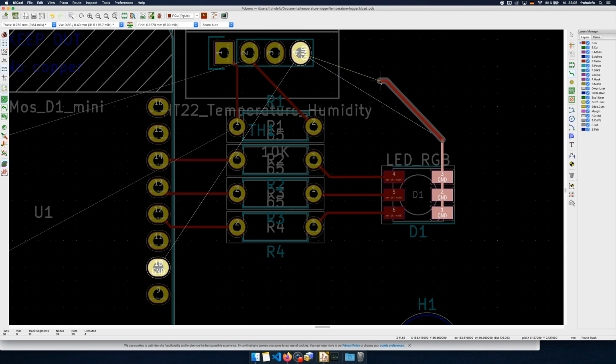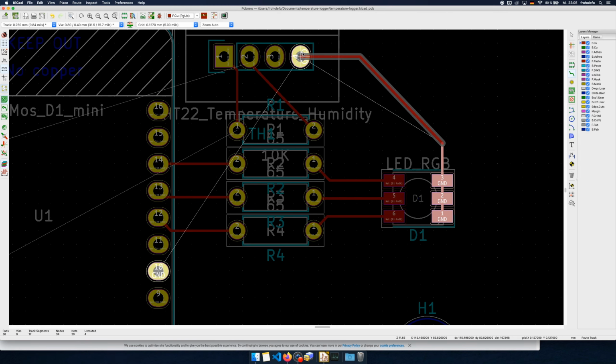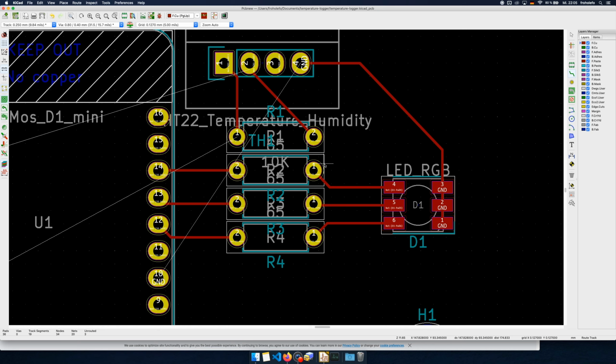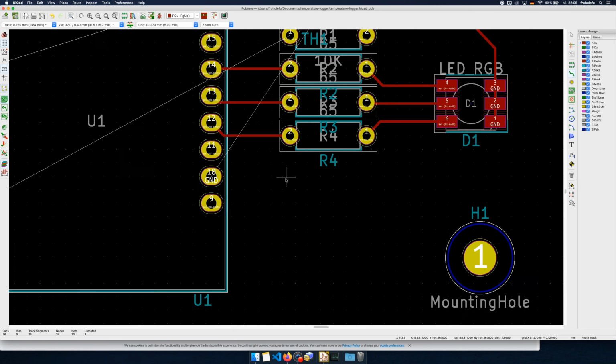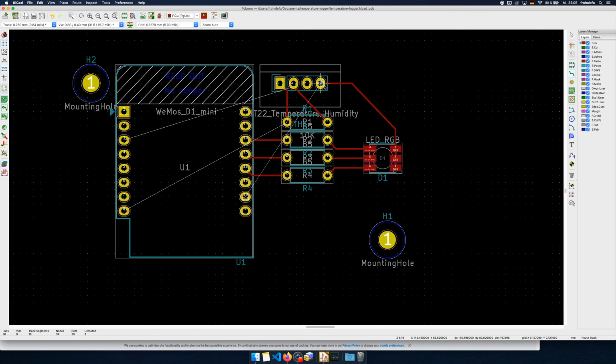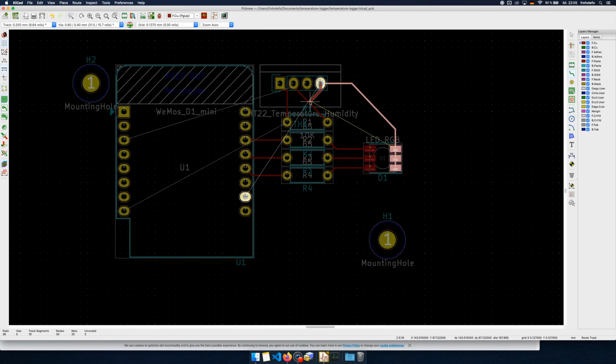We can also click, then it makes like a stop there. And so with an easy PCB, this is a pretty nice and convenient process. When your PCB is a little bit more complex, the routing can be super intense. Say now we want to connect, for example, this ground to this one, but the problem is that there are some red lines in the way.